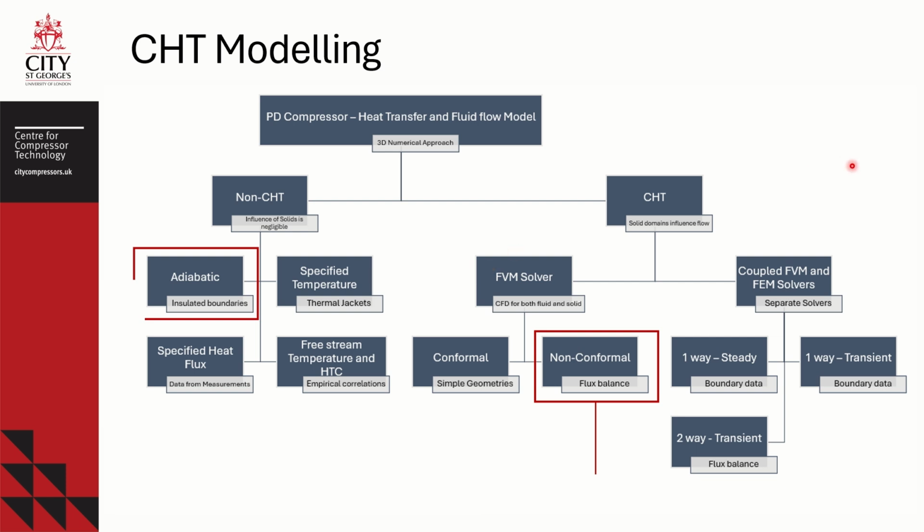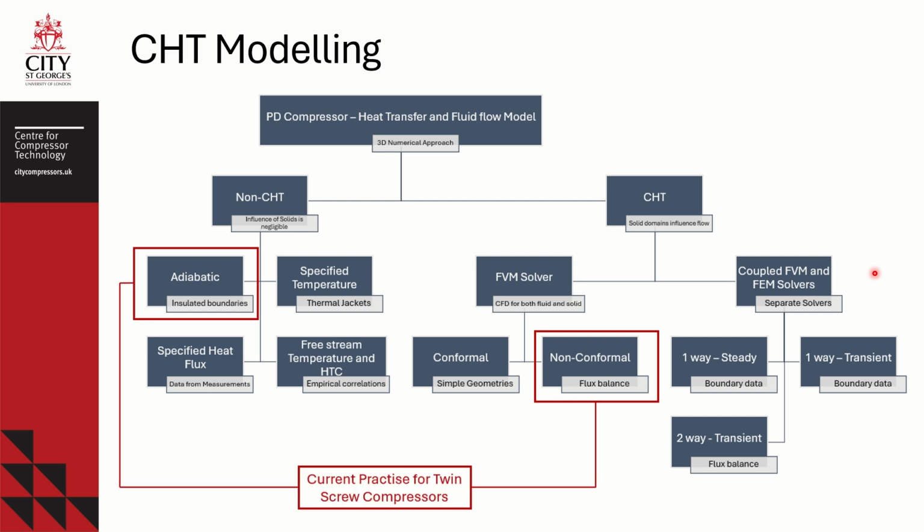Based on the solver that is used, you can have the whole problem formulated within the finite volume method solver. So a CFD model is used for both the fluid as well as solid. Or you can have a coupling algorithm where finite volume methods interact closely with finite element solvers for the conduction part of the solids. Current state of the art uses either adiabatic or finite volume method based conjugate heat transfer, most commonly for twin screw compressors.